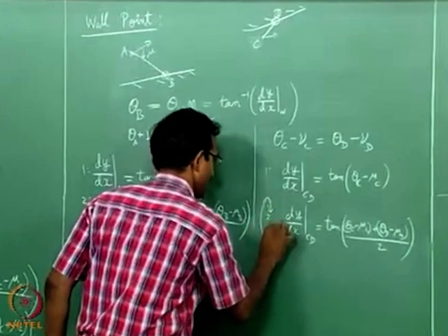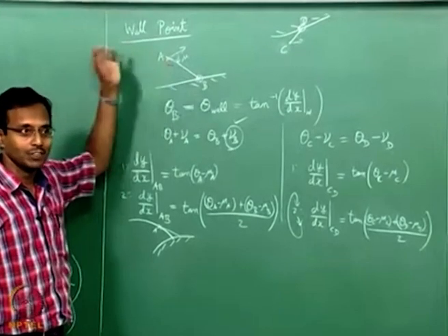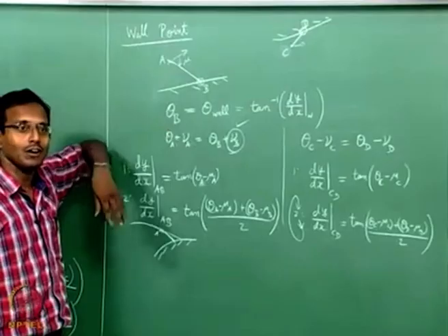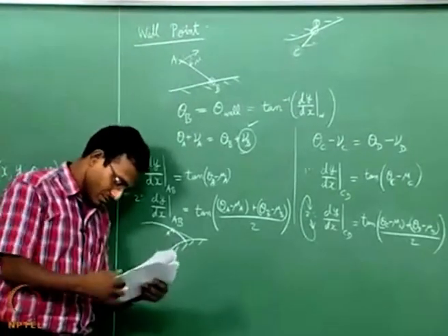across. You keep doing this several times. Step 2 is just done till you converge to slope doesn't change more than 1% kind of condition. Okay. And finally, that gives out your point B or point D depending on whether you are having right running characteristic hitting the wall or left running characteristic hitting the wall. Okay. And this gives you the next point.